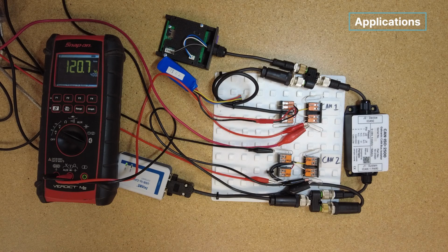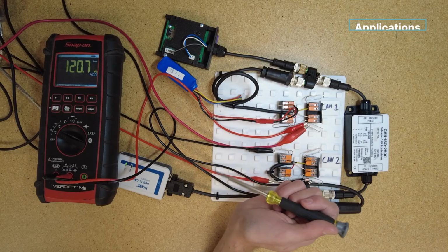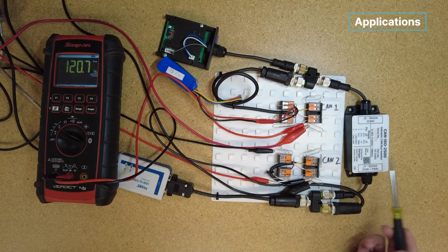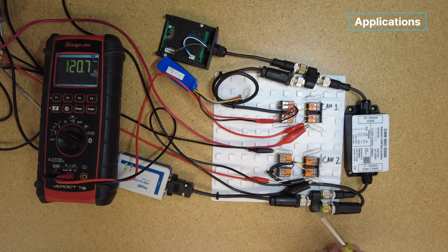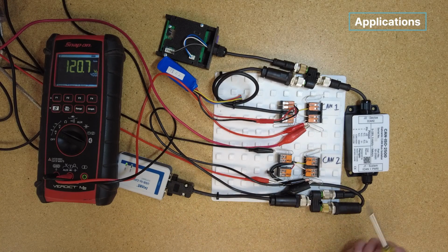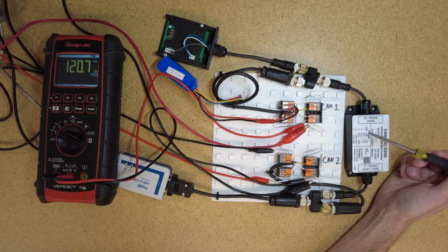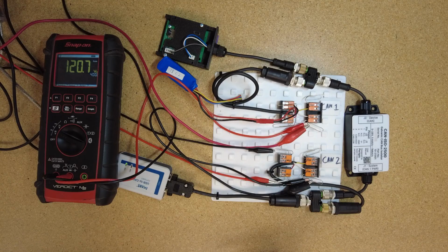One of the big applications for this sort of setup is where you have a high voltage motor controller. So say 96 volts or something like that, big, heavy, thick gauge wire, and that needs to be isolated with a device that needs to be separate from your control side. So this could be PLCs, HMIs, that sort of stuff on this side of the network, which are all going to be powered at between 5 and 24 to 28 volts DC. And then you have a high voltage or high power side of the network where you might have motor controllers, motor drives, VFDs, that sort of stuff, where you need some isolation because there's two different powering of the different devices on the network.